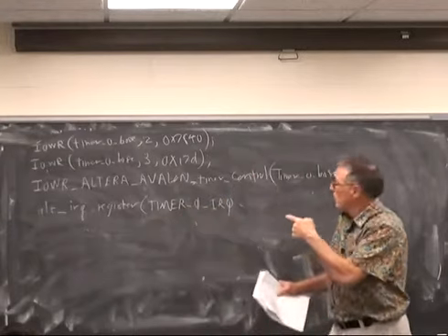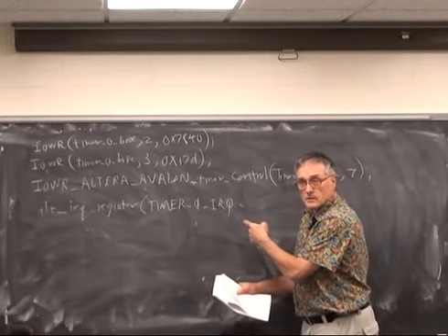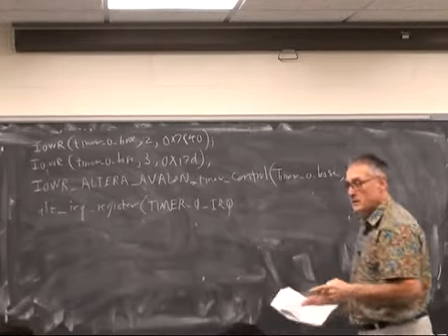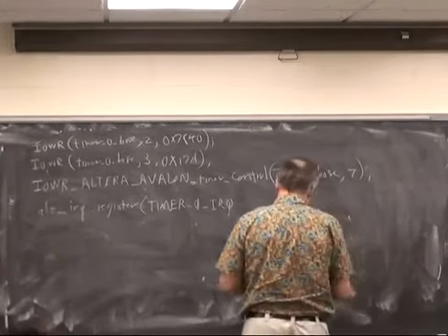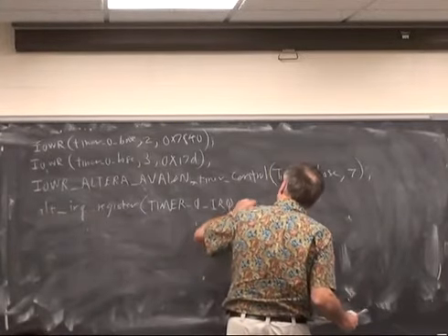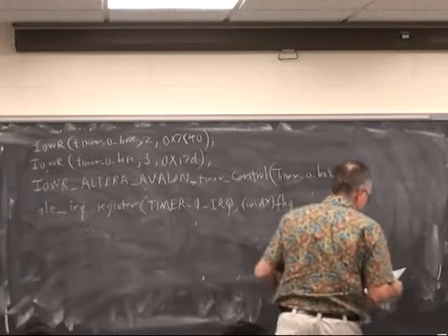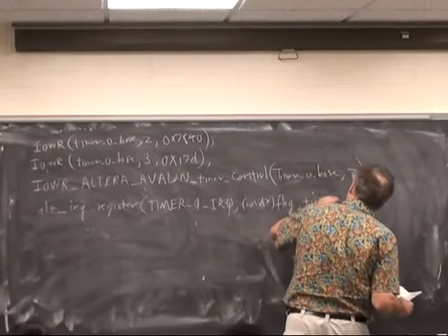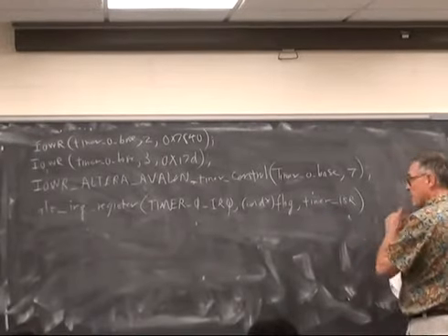That's another symbol that comes out of system.h. It's an interrupt number. We need to pass it a void pointer to flag, and we need to give it the name of the function that we wrote.